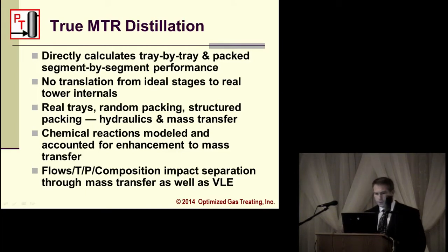Again, the purpose here is to educate you on mass transfer rate-based simulation. And when we get to that, true rate-based distillation, we're calculating directly the transfer of species in either packed segments or real trays, depending on the actual hardware that is in the system.